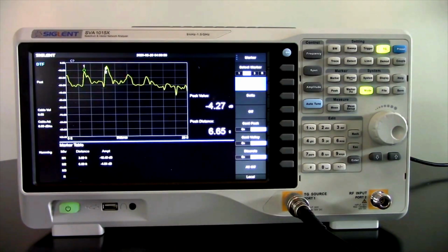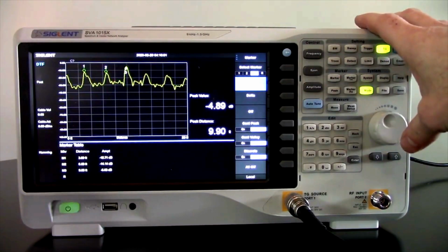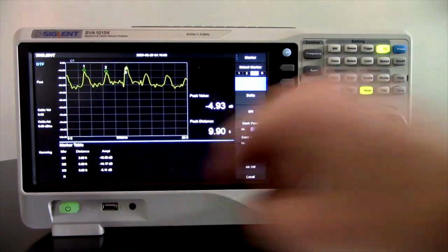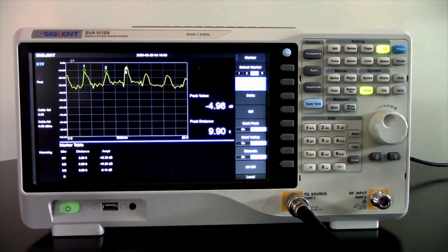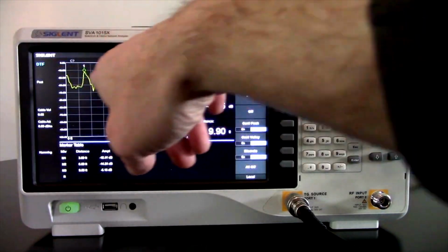Now I'm going to connect another chunk of cable here, and we'll be able to now see the third peak, and we'll just go to that. And you'll see now we added 9.86 feet. So now we have our total. All 3 of these peaks represent each of the cable adapter connections, basically measuring to that center line on that barrel adapter, and then they're all laid out for us.